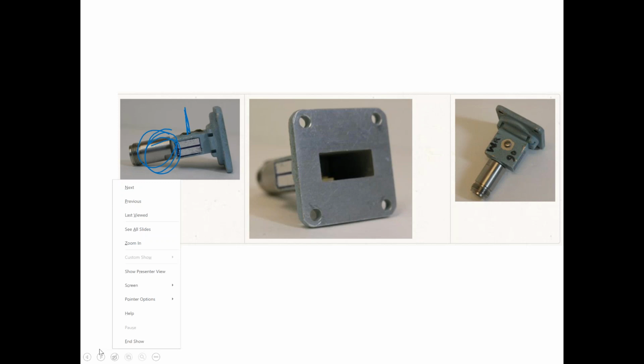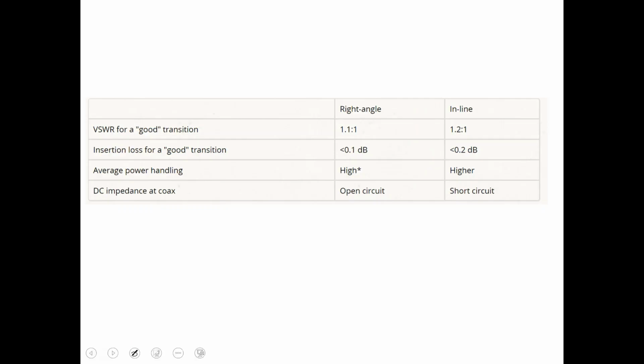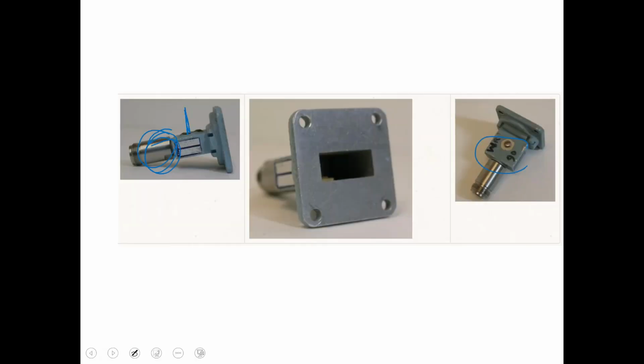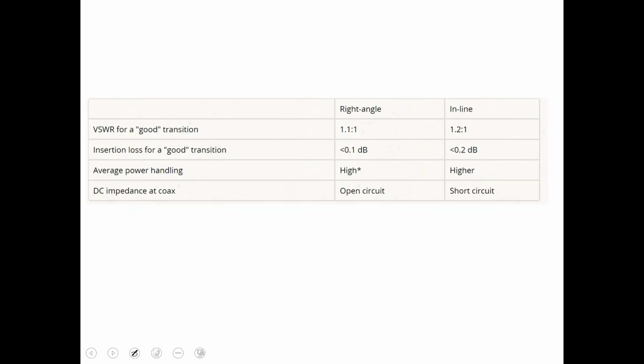This particular connector is a waveguide called WR90. This waveguide is used a lot for, I think, 5.6 gigahertz applications. But search for it, I'm just speaking out of memory. Search for WR90 and it will tell you what this waveguide looks like.